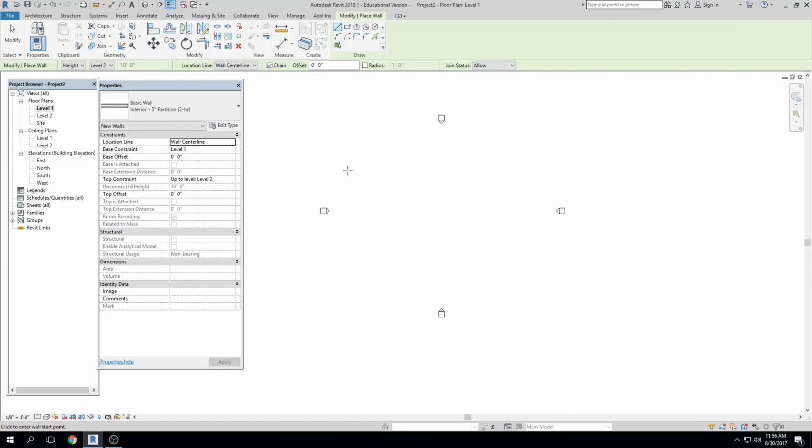It's okay. But you want to pay attention where you're drawing your walls from, right? Because it makes a big difference. Your client is like, I can only have 100 square feet. That is it. No less, no more, like right on 100 square feet. You're going to want to draw, and we'll say that's the interior space, from finished face interior, right? So you get a 10 by 10 or whatever equals 100 square feet of space in there. If you draw from the outside, you can have more space on the inside or less space on the inside because of the wall assembly, right? So where you're drawing from is a big deal, okay?